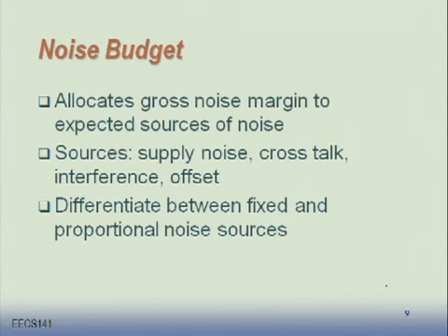We'll tolerate supply noise of up to about 5% of VDD, and you'll get that target from your management team, or if you become a manager one day, you'll give your designers a target that you have to keep the supply noise less than 5% of VDD. We go to tolerating 15 millivolts of supply noise, and so on.